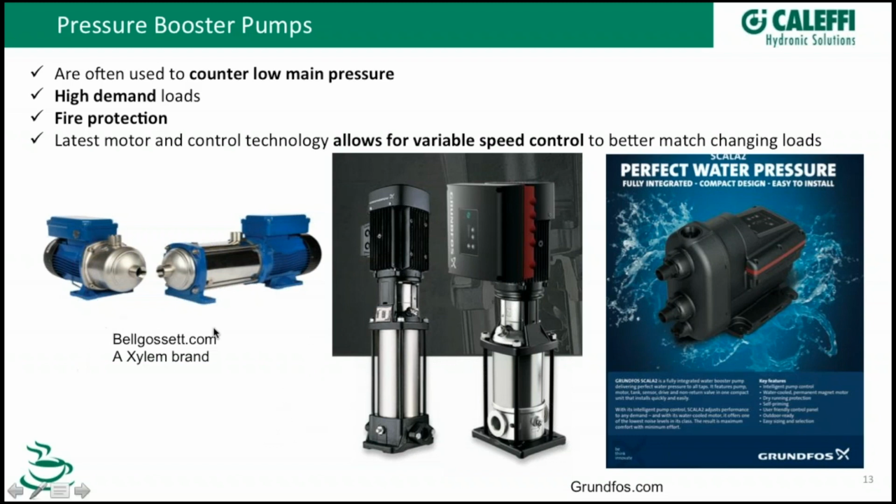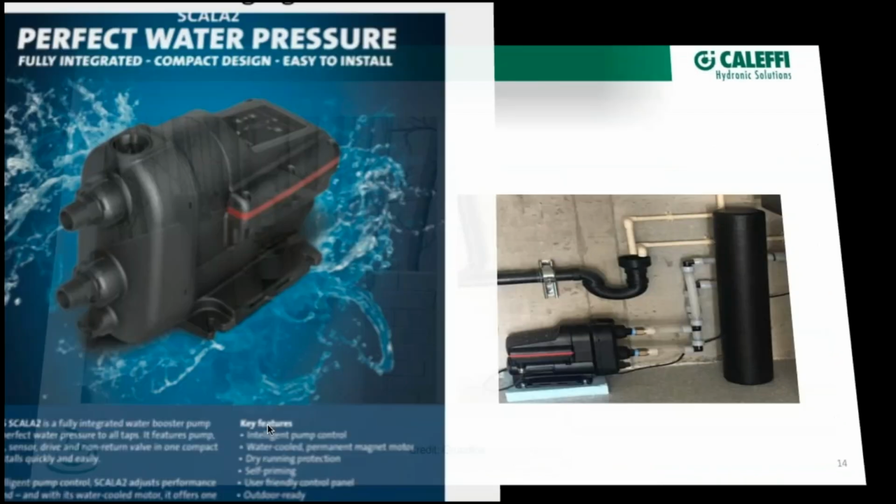Now, examples of where you'd want to put a booster pump: maybe you've got adequate pressure in the house for the fixtures and stuff like that, but you might have a fire protection system that, if that went off, you've got to make sure you've got adequate flow for the heads that are triggered off. Or another high demand load, like, oh, I don't know, maybe a lawn sprinkler system outside, where when all the heads are coming on, you've got to make sure that you've got enough flow and enough pressure to maintain all that. So these booster pumps you'll see used occasionally on jobs.